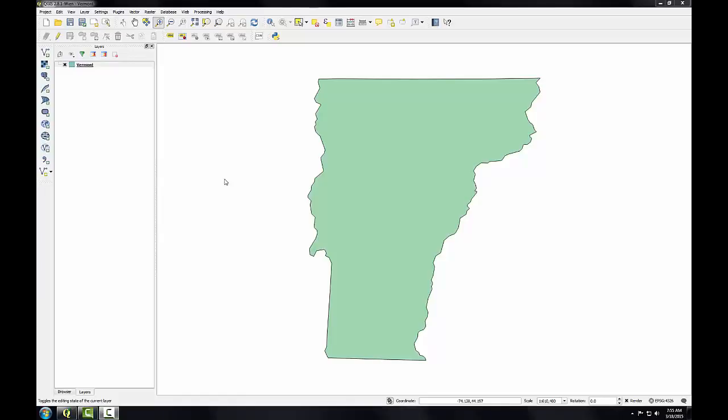It's actually a series of separate coordinate systems, each covering either an entire state or a portion of a state, depending on the size. State plane is only used in the United States, so it isn't appropriate or even possible to use state plane in other countries or regions of the world. It's popular due to its high accuracy in large-scale mapping because of the relatively small size of each zone. The zones are so small that you're not having to flatten out as much curvature of the Earth as you are, say, with a map of the entire lower 48.